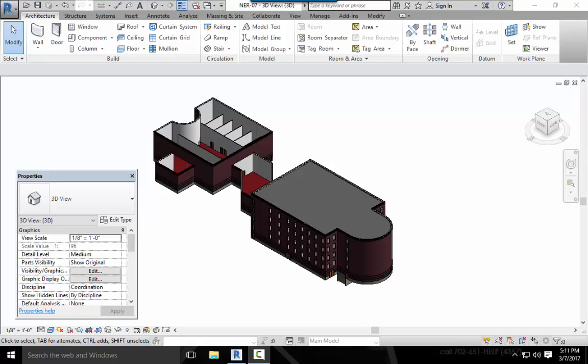Alright, so we're starting at figure 7.20. We finished the roof over here on the east wing. We're really going to be focused on this roof here and putting roofs on the rest of the building for the remainder of the chapter. Many of the procedures are almost identical to what we've already done, but minor things will result in slightly different roofs. So first thing we're going to do is put a pitched roof or a gabled roof on this corridor area. So item 1, go to a 3D view of the model.